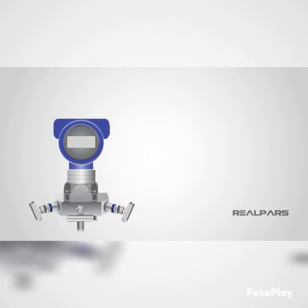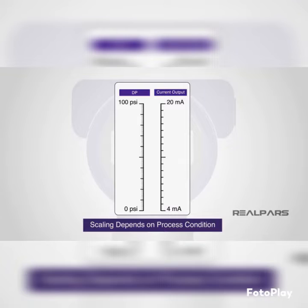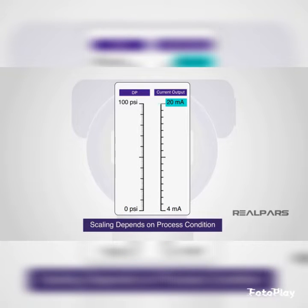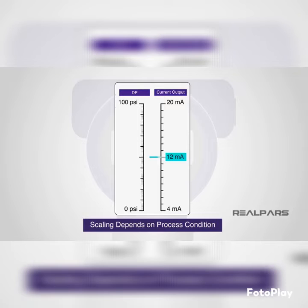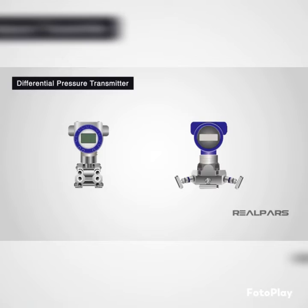The electrical output generated by the dP transmitter electronic module is linear and proportional to the actual measured delta P. Depending on the range of measured pressure, a 4 milliamp signal would equal a measured delta P of 0 psi, and a 20 milliamp signal would equal the maximum measurable value. In this case, we'll say that the maximum delta P is 100 psi. Using these variables, we would know that a 12 milliamp signal would equal 50 psi delta P. The relationship of the produced electrical signal to the units of measure is called the scaled output.